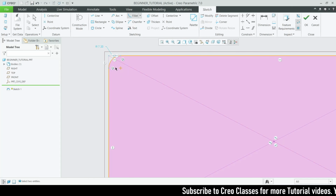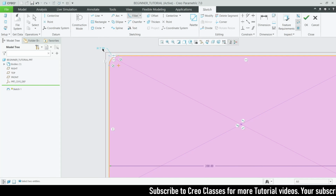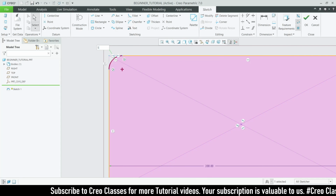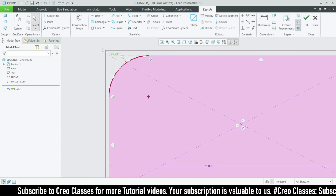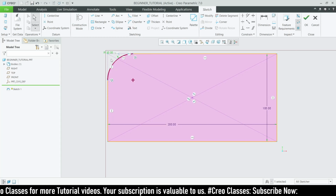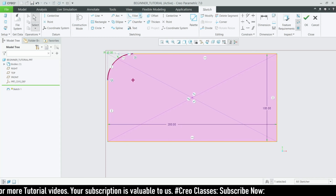As you can see, it is turned into a round feature. By clicking the escape key, you can also edit this radius value, so it will increase the bend radius, like curved edges.